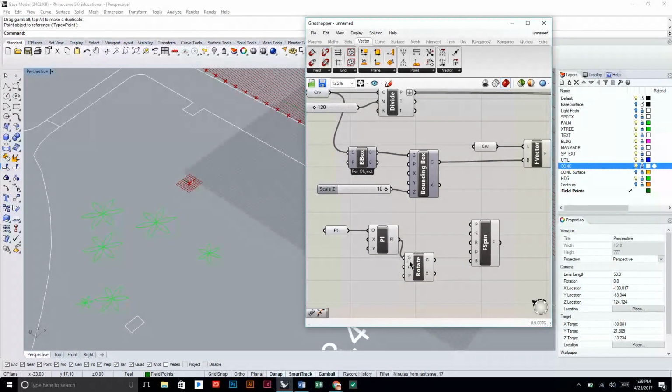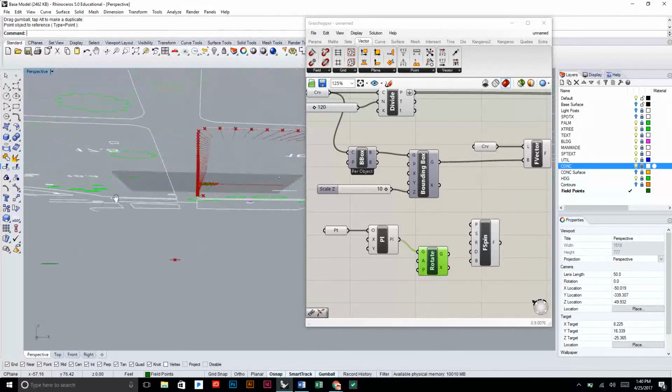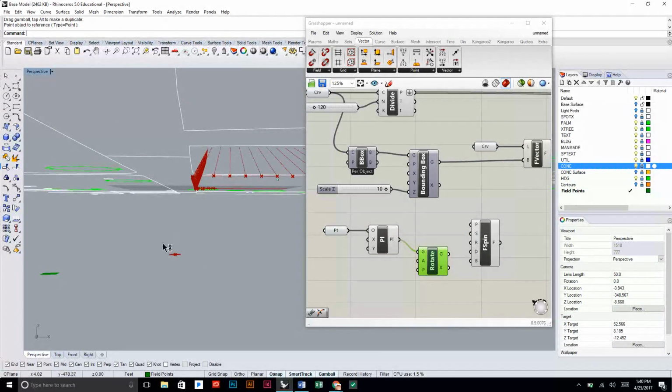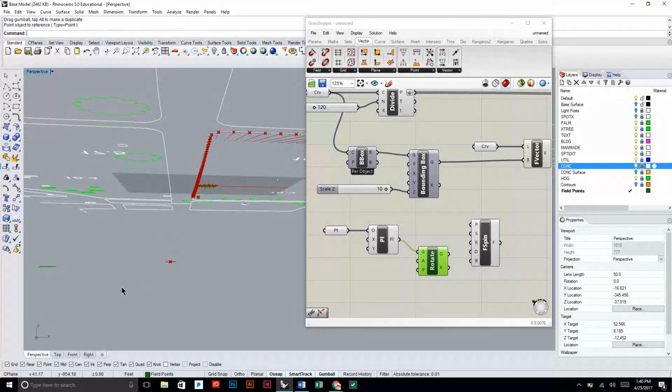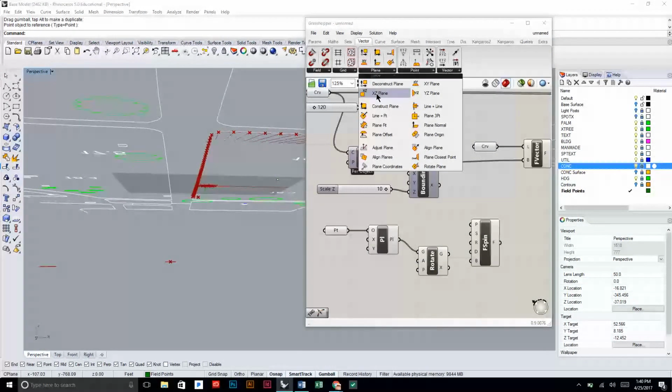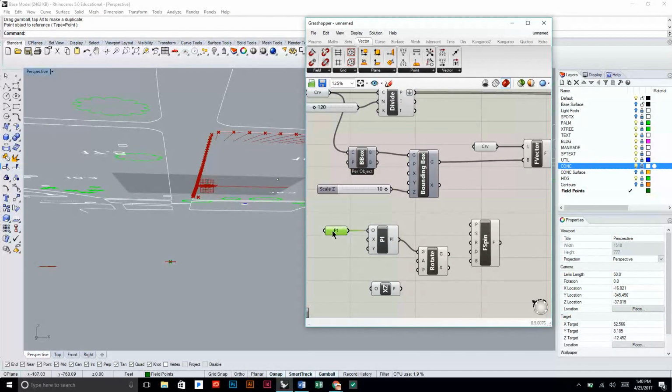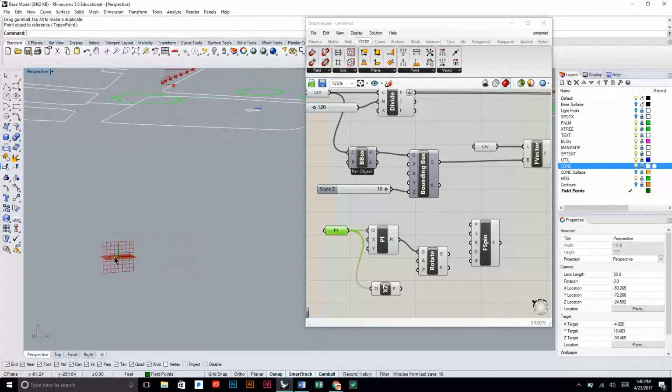So I'm going to spin that geometry. I need to know a plane to rotate it on. So I want to spin this so that it starts to kind of go in this direction. So that's going to require a ZX plane. So I'll stay with here. I'll choose plane and use the XZ plane. I'm going to also drag this into the origin there. So you can see now these are intersecting with one another. I'll drag this into the plane input here.